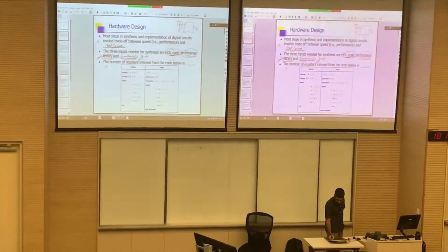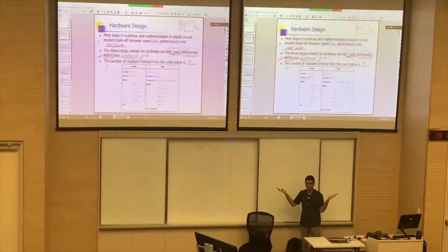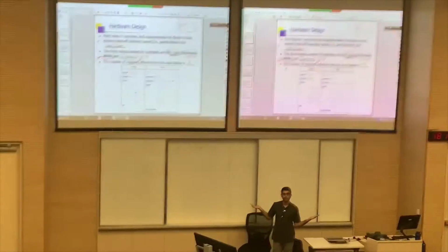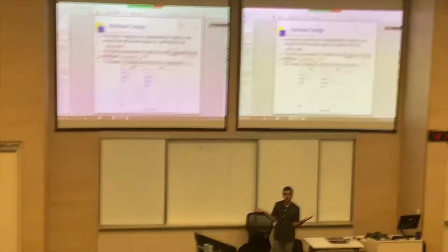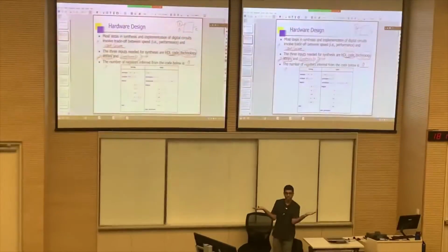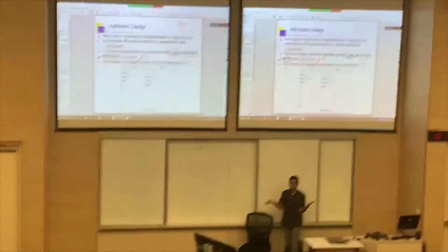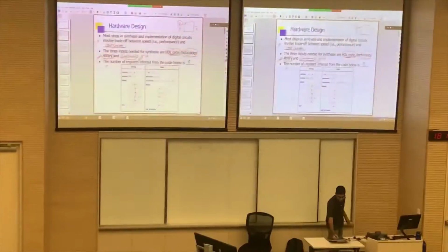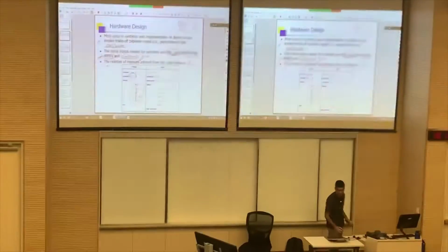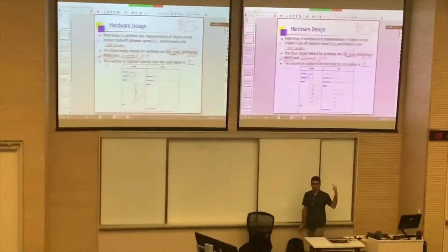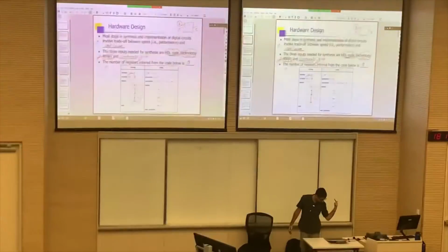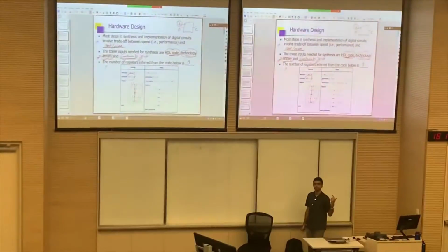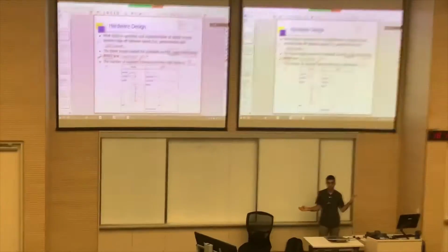Yeah, 0. Because you can see there is no clock involved at all. It's a purely combinational circuit. There is no posedge, negedge clock or anything of that sort. All outputs are sum of product or product of sum expressions of all inputs. So here P, Q and Z are inputs and A, B, C, D, E are outputs. It's a purely combinational circuit.